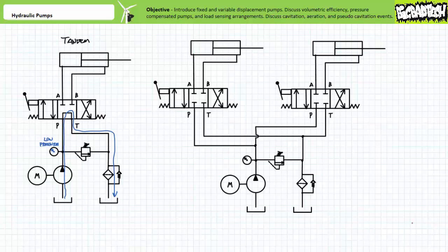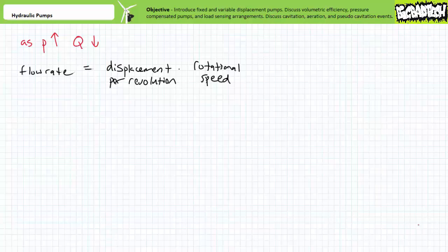We'll examine alternative circuits making use of closed-center directional control valves that prevent actuation of the pressure relief valve, making use of pressure-compensated pumps in a moment. The fundamental confusion about the role of pumps in hydraulic systems largely comes from pump performance characteristics, which demonstrate that flow rate produced by a pump is ordinarily a function of pressure.